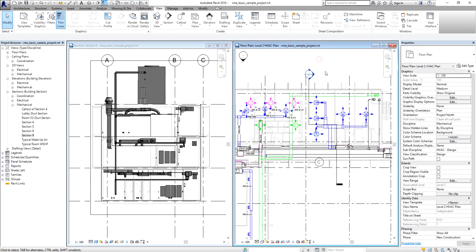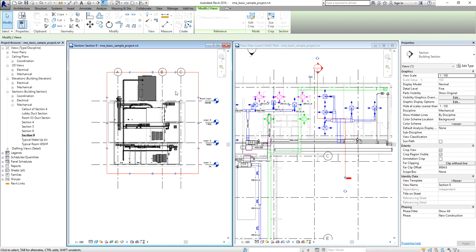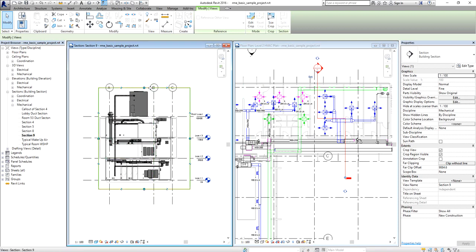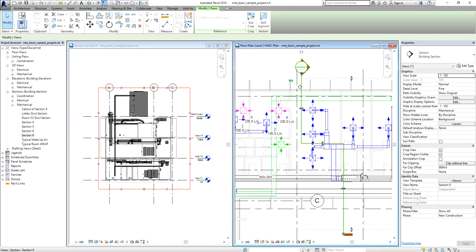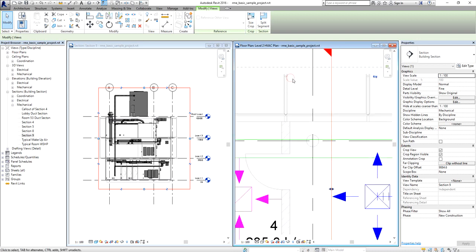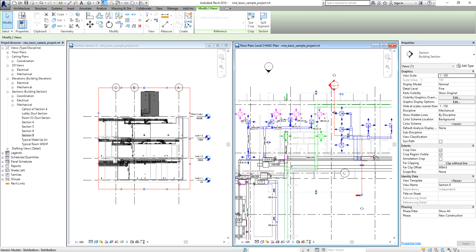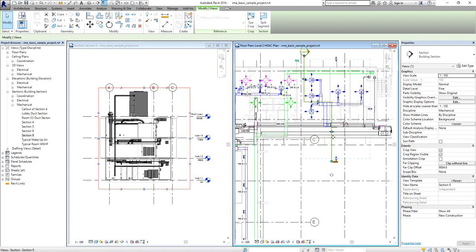Okay. So as you can see, if I select the section, you'll notice that the boundary here on your section is highlighted also. So you can control the section on your floor plan from here also. You can also flip your section. If you click this, you can flip to the other side. Just like this one, you will notice it updates also. So when you flip that, see it updates. Now, if you want to go back to a straight section again, all you have to do is drag this handle. There you go. So it's now straight again.